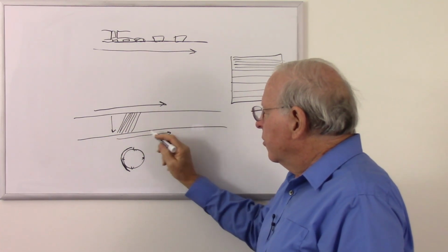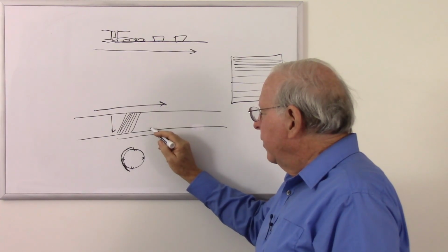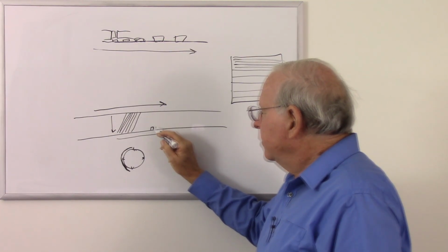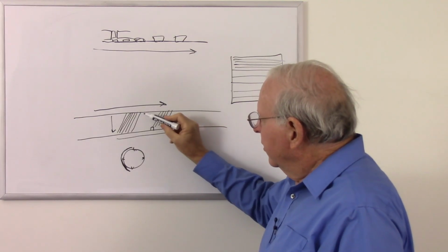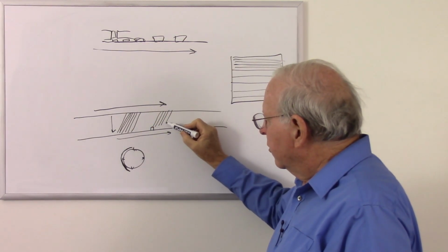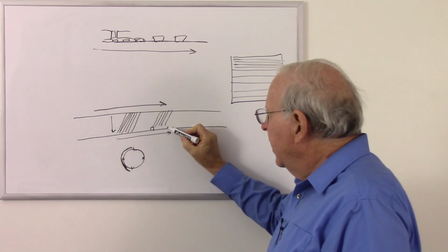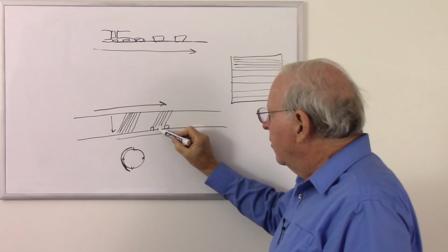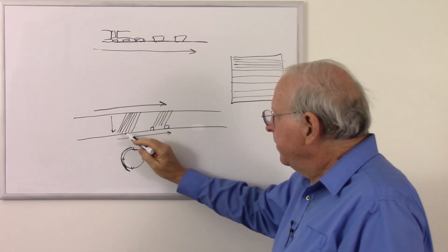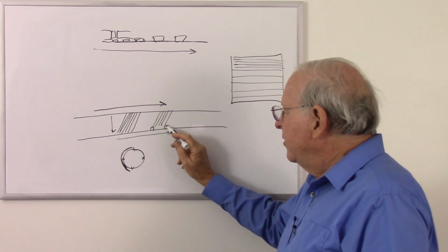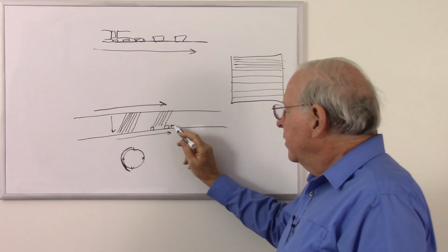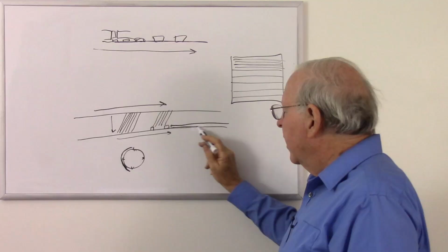Then after that was recorded, it would go by an erase head on the edge, which would erase part of that. So we're actually scanning more than 16 lines. We have a little bit extra here that we can erase. And then past that was a record head. So the tape is going this way. We scan the TV lines on there, then we erase part of the edge, and then we record the audio like standard audio tape in a track on the edge.